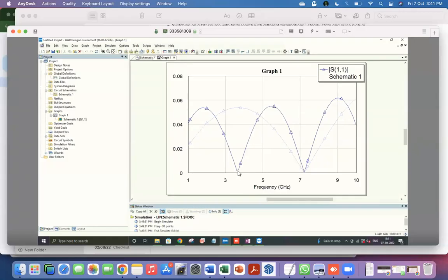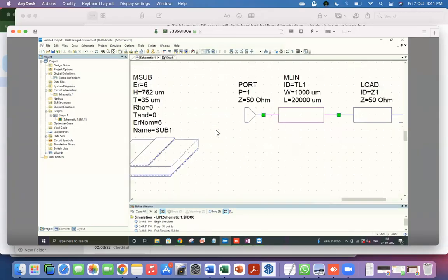You can sort of see from here, this frequency and these frequencies are related by a factor of 2, right? So, what does this mean? That at these frequencies, there is zero reflection at this point, which means that this whole thing looks like 50 ohms. Now we know that this is 50 ohms on this side. So this we know is 50 ohms.